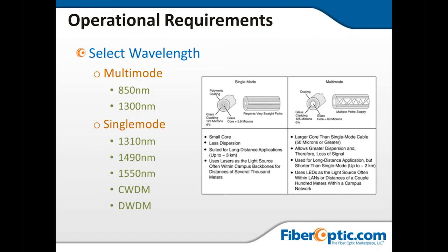Then you've got to look at, if you're going with single mode, one of the factors for upgrading existing fiber is using wavelength division multiplexing. If you've got existing fiber that goes where you want it to go, but you need more signals, one of your options is not in the glass itself, but in the hardware on either end. And if you can take one dark fiber and put wavelength division multiplexing on it, you can run multiple existing signals, even with disparate types of technologies.